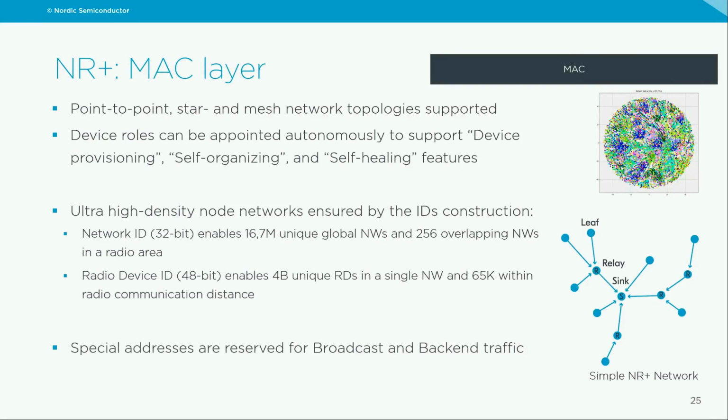So this is typically built in the MAC layer. So you have autonomous device provisioning and also self-organizing and self-healing features just in the MAC layer. So you don't need to do anything special on the application layer or any top layer because this is handled here. And this makes the technology very nice with regards to reliability and that you don't have any failure points.